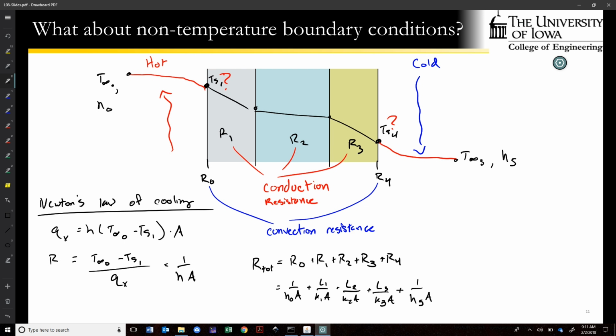Let's say you have a situation like that, where there's a constricted amount of heat flowing through a wall. With this approach, you can then calculate the temperature difference from one side of the wall to the other. So it's a very elegant and practical approach to conduction analysis.